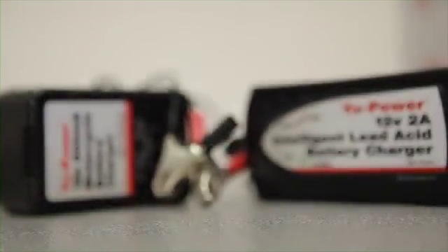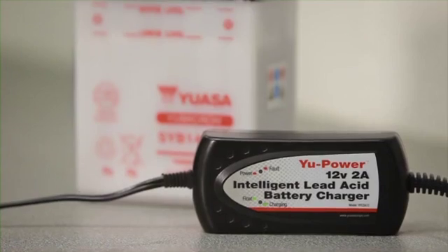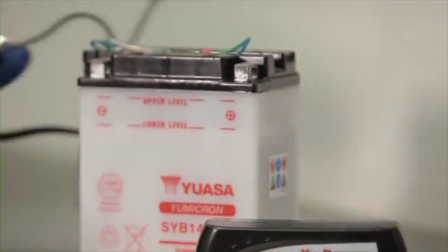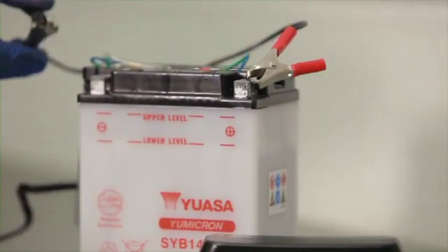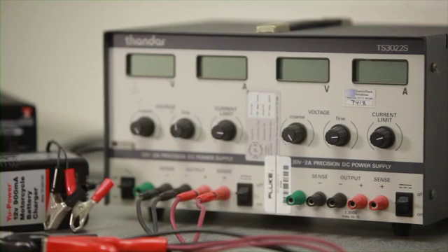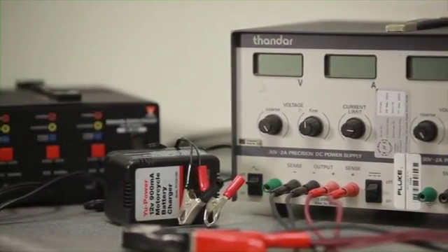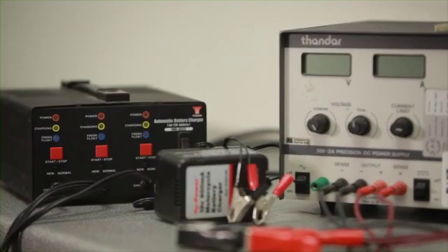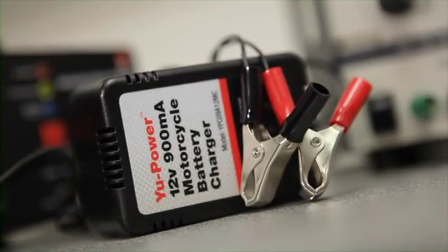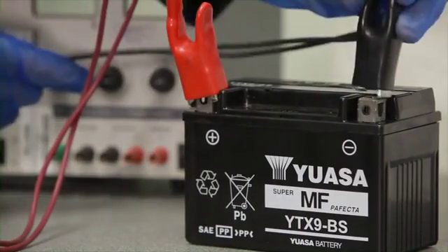Other types, such as trickle and taper chargers, are best used as maintenance chargers and are also suitable for domestic use. Always consult the instructions included with the charger for proper operating procedures. Be sure the charger meets the needs of the battery you're charging. Sealed-type batteries require a higher voltage charger than conventional types. Proper charging is essential to ensure maximum operational capacity and longevity of a new battery. It also helps prevent electrolyte leaks that may damage a vehicle.